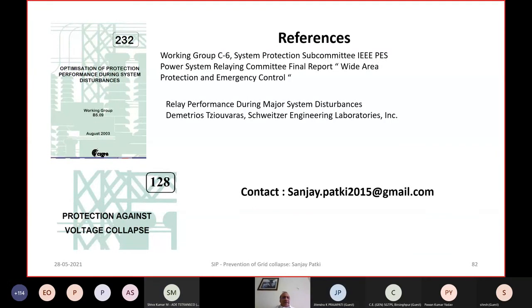Both main one and main two are independently measuring the distance to fault, and they should normally give within, say, accuracy of nowadays they say even 2 tower lengths. So I am not getting your question, but both will independently give the distance to fault. So there should be reasonable matching between the two distances. Do you find that the distances measured in the two relays are quite different?